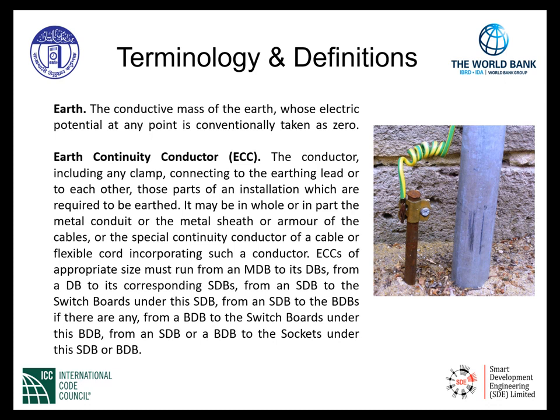The term Earth is the conductive mass of the Earth, whose electric potential at any point is conventionally taken as 0. Earth continuity conductor, abbreviated as ECC, is the conductor including any clamp connecting to the earthing lead or to each other, those parts of an installation which are required to be earthed. It may be in whole or in part the metal conduit or the metal sheath or armor of the cables,